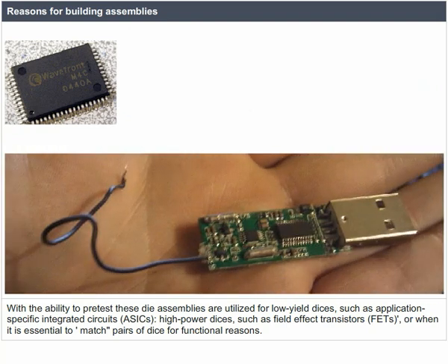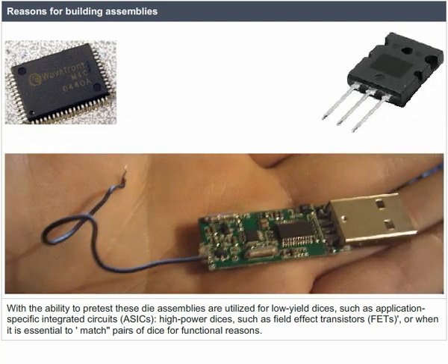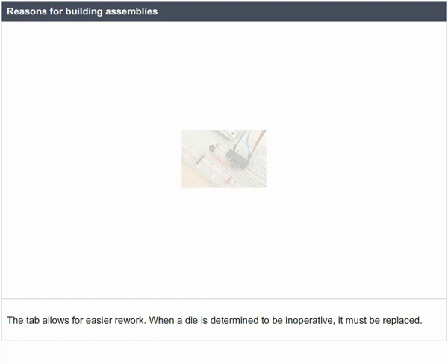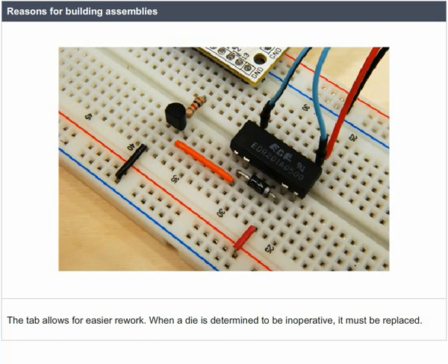With the ability to pretest, these die assemblies are utilized for low-yield dies, such as application-specific integrated circuits, high-power dies, such as field effect transistors, FETs, or when it is essential to match pairs of dies for functional reasons. The tab allows for easier rework.